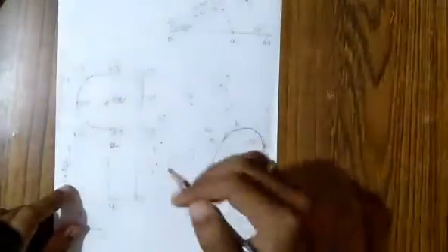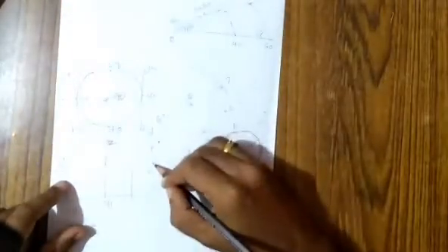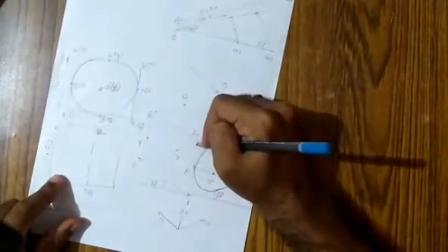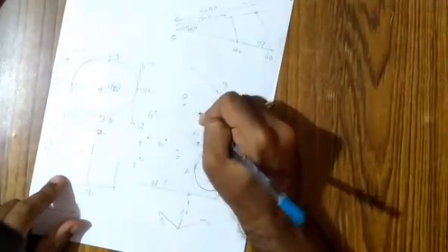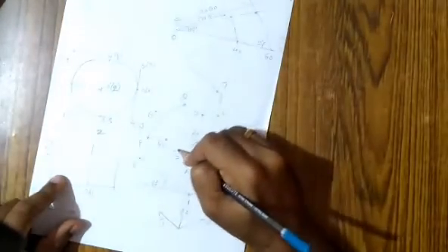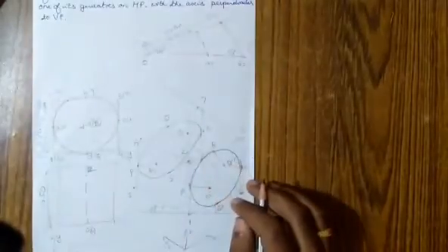So this is the front circular face which will appear as an ellipse. Okay, now the back circular face, you apply the same procedure as we said, the major diagonal, the minor diagonal. From the minor diagonal vertex you connect to the opposite midpoints. From 6 you connect to S, and from 6 you connect to R. You have O3 and O4. Okay, O4. You repeat the same procedure which we did earlier. Okay, so you will get the back rectangular face.